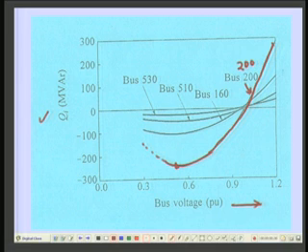Now, these are the different types of QV curves which have been shown, and as we will see in our further discussion, the slope of this curve, or you can say the QV sensitivity, will be a very important indicator for analyzing the voltage stability of a system.